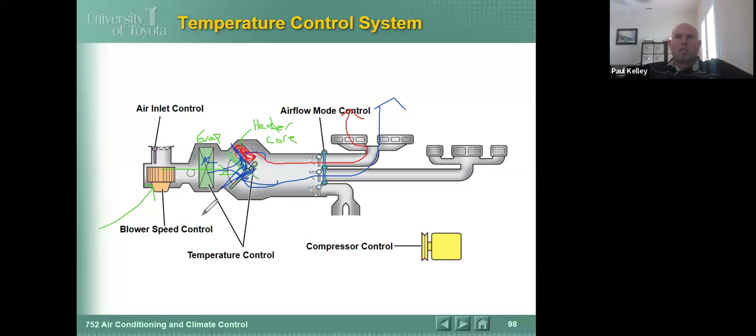Now, Madi brought up a good question. With this heater core or with this evaporator, we have refrigerant going in, we have refrigerant coming out. And let's just say the evaporator starts to get warm, we want to cool it off, right? So generally what we would do is we're going to close off the TXV, which is going to drop the pressure more. And the lower the pressure, the lower the temperature. But in fairness, and Madi, when you watch that video, what did it tell you?